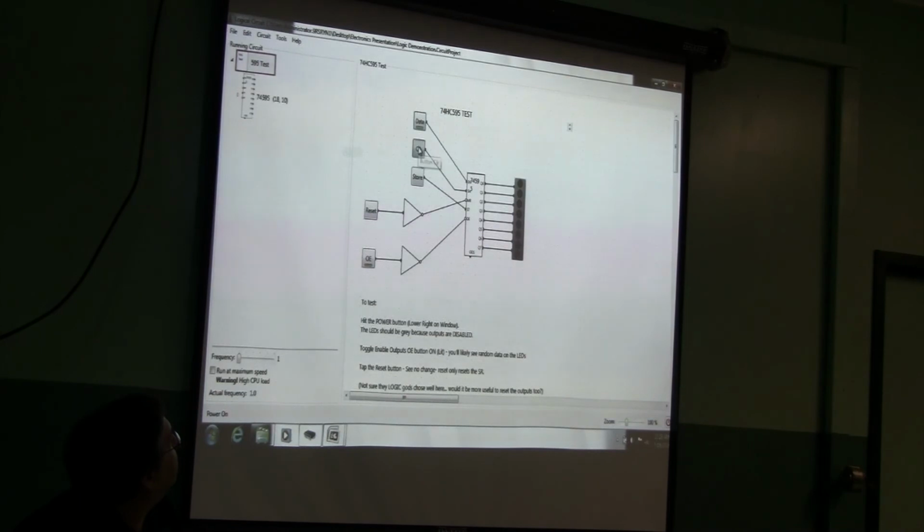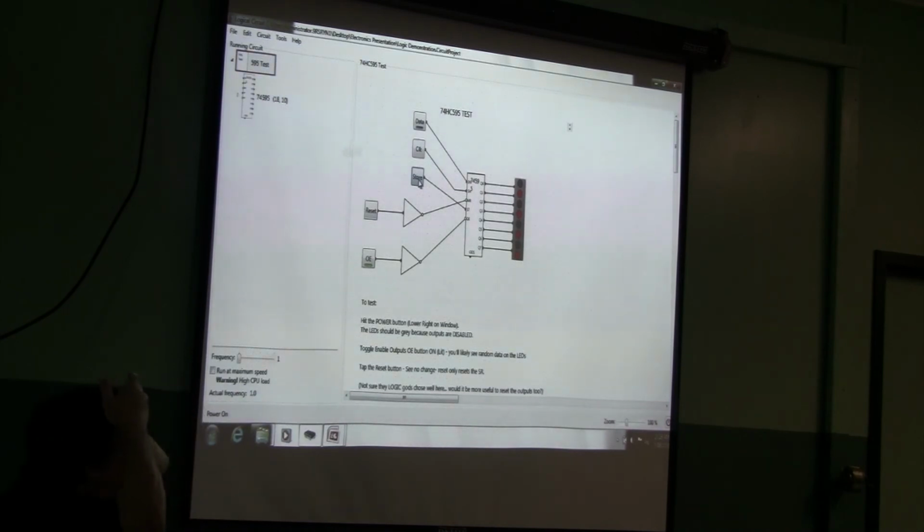So I go 1, clock it in. 0, clock it in. 3, 4, 5, 6, 7, 8, and then store. There you go. So it's called a shift register. Basically, it's one way of taking serial data and turning it into parallel data. Parallel means all 8 bits at once, serial data is 1 bit at a time. So that's another handy thing.